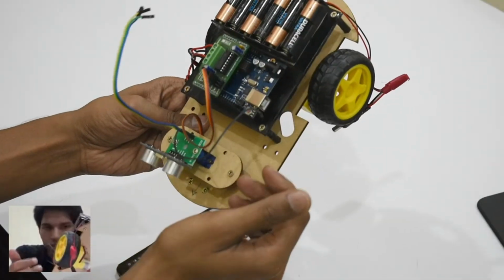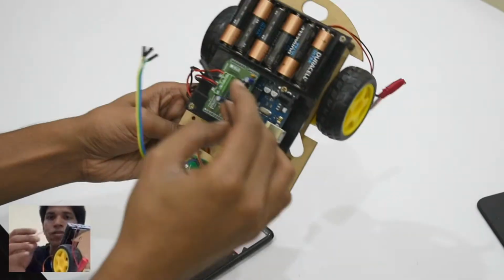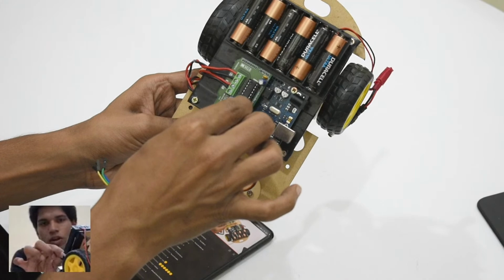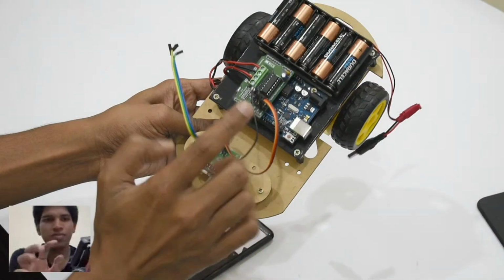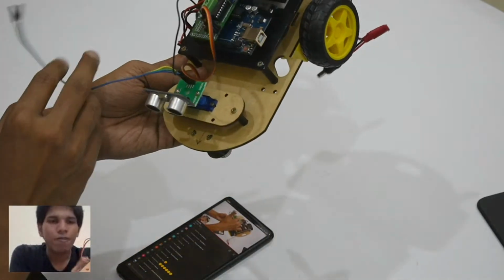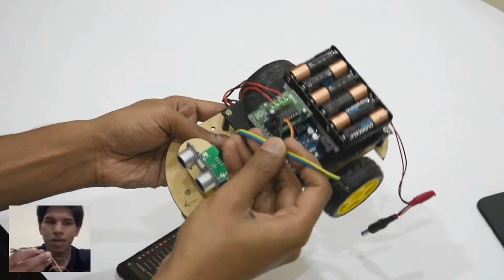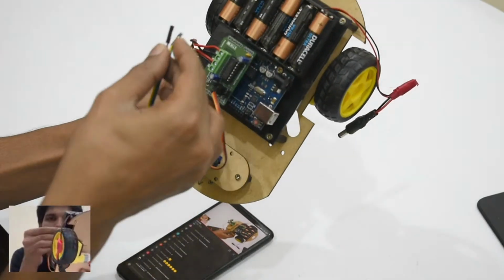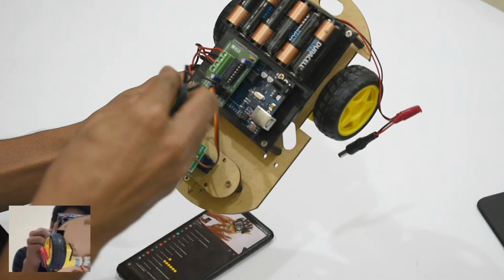Now ultrasonic sensor again has 4 pins, so it has a ground and 5-volt pin. So ground, again as usual, there are some ground pins here. You can attach to any of these. So I'm attaching my ground pin of the ultrasonic sensor to the ground pin here. And other than that, I have the 5-volt pin, that is my yellow wire here. I'm just simply going to attach the yellow wire to the 5 volts supply here.